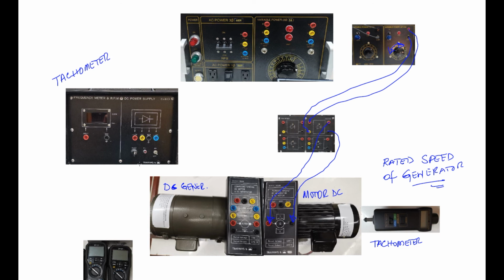Going back now to this generator, how can we excite the generator? Look, we have two elements here: the field winding and the armature. So those are the terminals that will be used. The field and the armature. This is shunt. If we use this one as a motor, a shunt motor, we have to put these ones here in parallel.